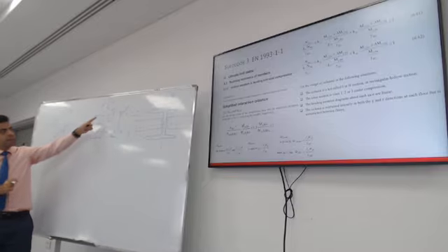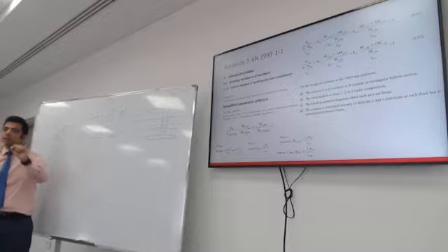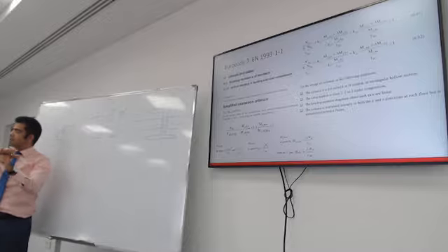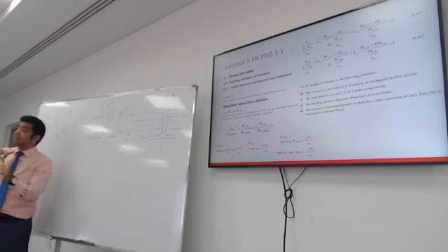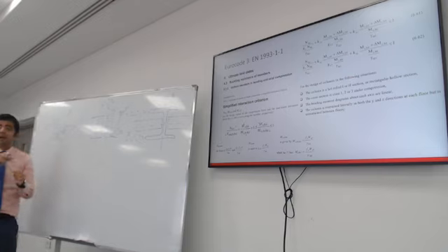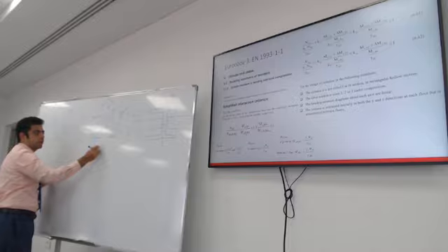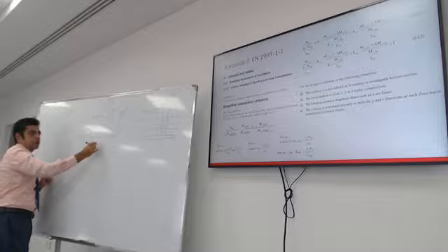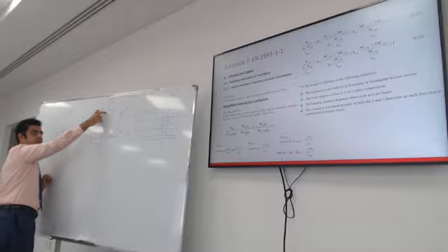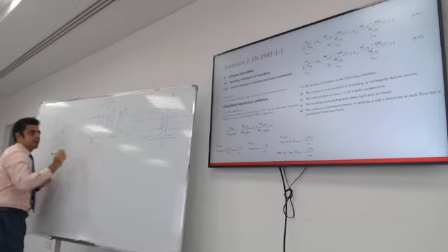So in a way, that corner over there is feeling the axial stress from the axial load, and on top of it, the moment is stressing it even further. And if you do the analysis for My, you get another similar diagram with compression at the tip of the arrow and tension at the tail of the arrow.